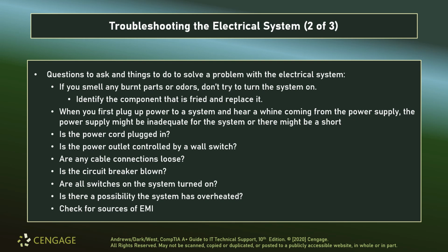Questions to ask, of course. If you smell anything burnt, don't try and turn the system on. Let's go ahead and replace that fried component first. If we hear a whine, it may not necessarily be that the system is too weak. It may also be that there's a short. Again, check your simple stuff first.